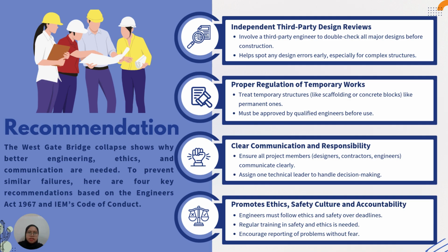My name is Izzati and I will present the recommendation and conclusion. For recommendation, first, involve an independent third-party engineer to double-check all major designs before construction. This helps to catch any design error early, especially for complex structures. Second, apply proper regulation of temporary works such as scaffolding or concrete blocks, which should be treated just like permanent structures. They must be approved by a qualified engineer before use.